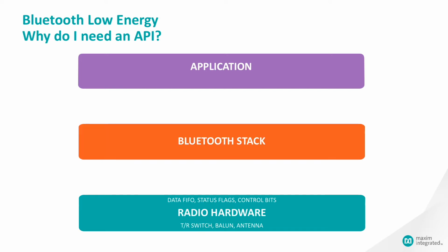The Bluetooth stack contains all of the mechanisms to implement the protocols that collectively are known as Bluetooth. It's all the stuff we've covered so far, and a lot more. But because Bluetooth is so complex and so intricately intertwined, the best solution is to use a stack built by experts. Now, the stack has to talk to the radio hardware to modulate Bluetooth-compliant signals onto the RF carrier, and it has to interface to the application to deliver the bits of information that the application demands.